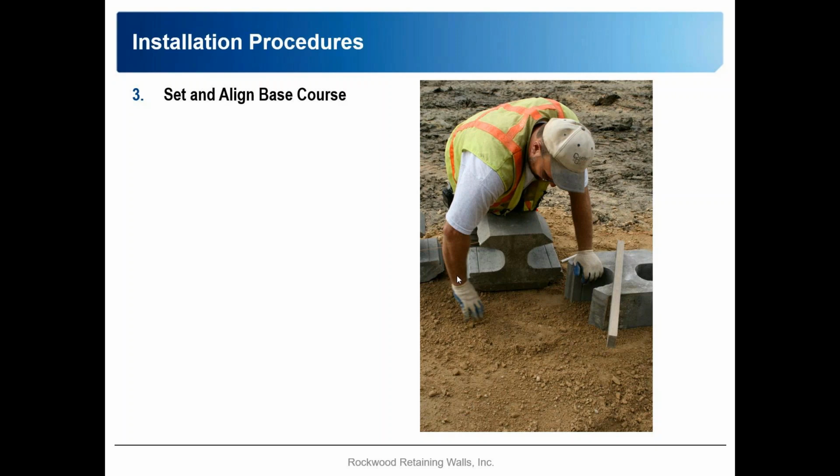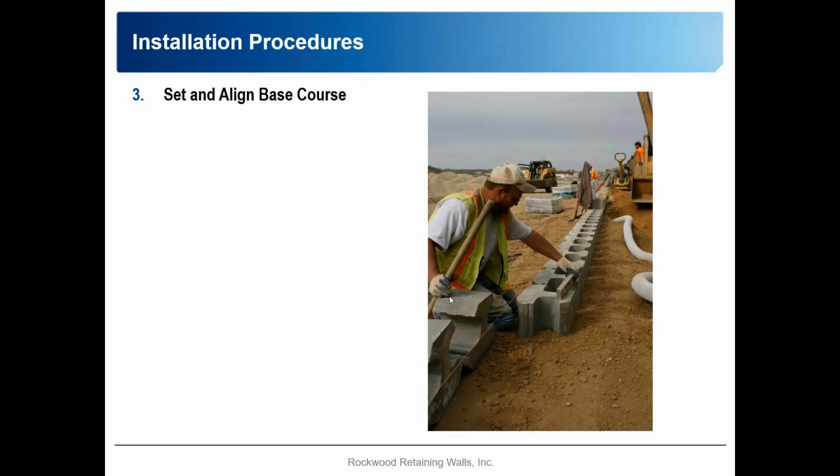Because what would happen is, if you're at 3/16 of an inch batter on this block, and then the next one's at a 1/2 inch, and then the next one's at an 1/8 inch, the tails aren't level. When you place the additional course of block and slide it forward, it's not going to engage in the same spot, and that will affect the wall alignment as you look down the wall. So it's important that if you are going to drop the tails or make those adjustments, that is done consistently.